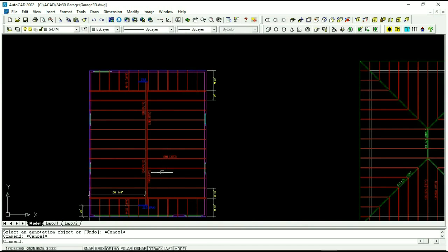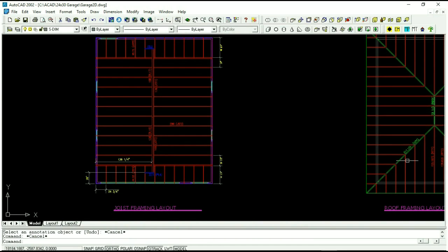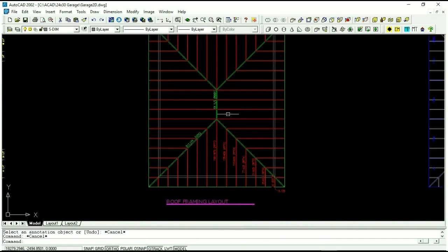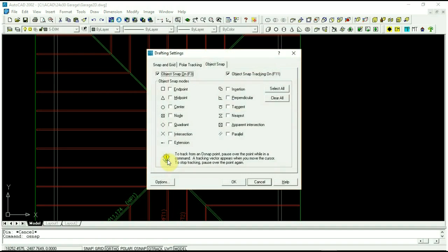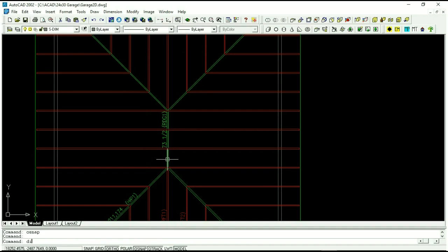So I'm going to make this joist, I'm going to make a stud, I'm going to make the hip, and I'm going to make this common rafter. To figure out the hip length and the rafter length, basically you just have to find the horizontal run from the face of the ridge to the edge of the wall. So it's 143 and a quarter, and you need that in feet. So 143 and a quarter in feet is 11.9375.